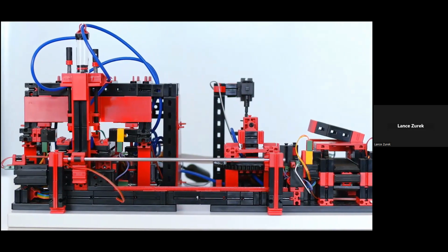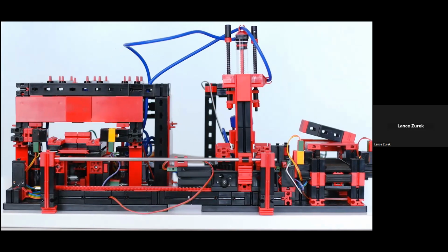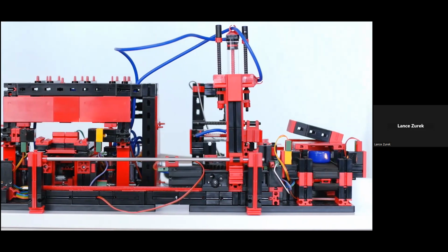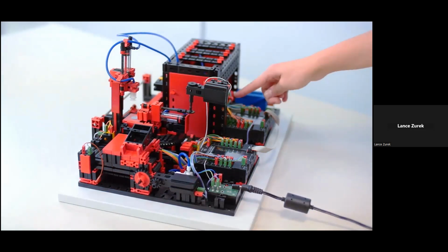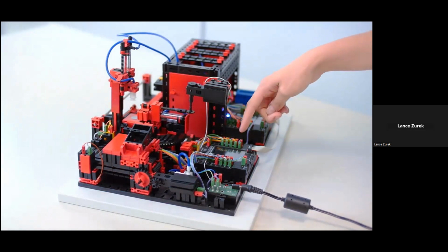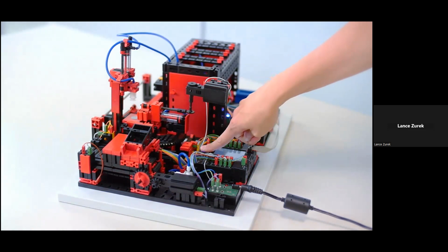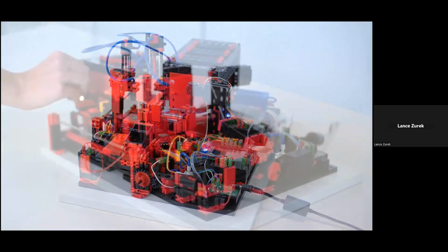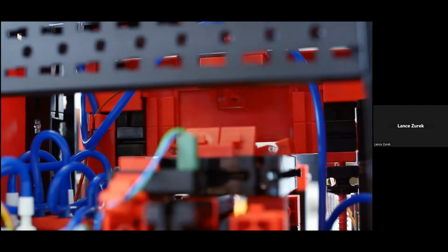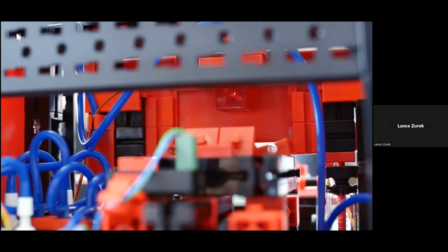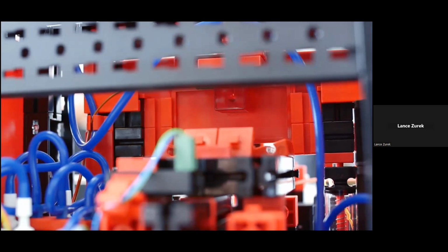Components found on this model include 4 mini motors, 6 push-button limit switches, 2 photo transistors, 2 LED light barriers, 4 solenoid valves, and a compressor. The dimensions for the model are approximately 20 by 14 by 12 inches, and it has a weight of just about 11 pounds.